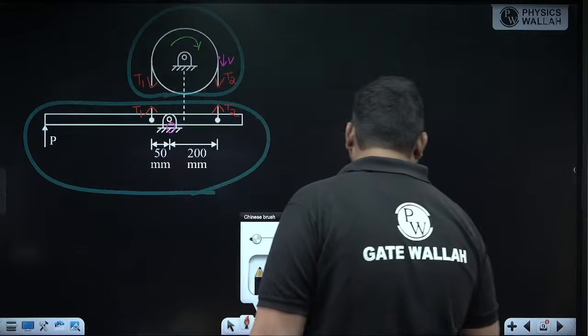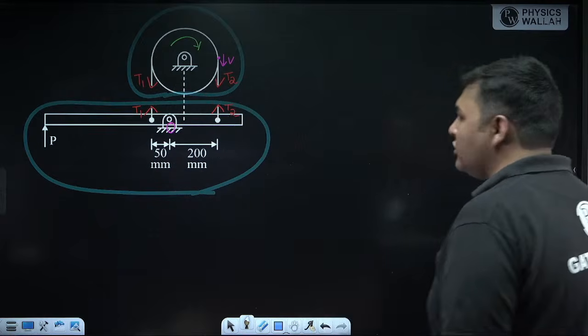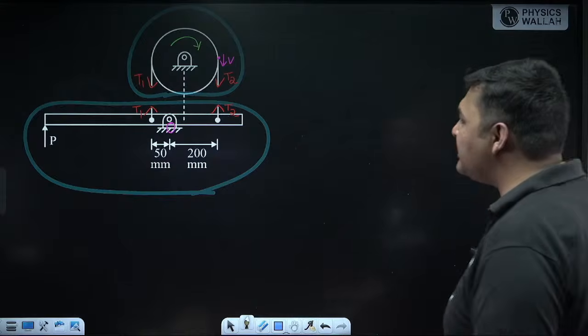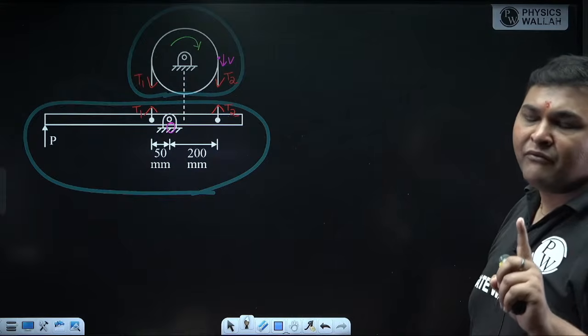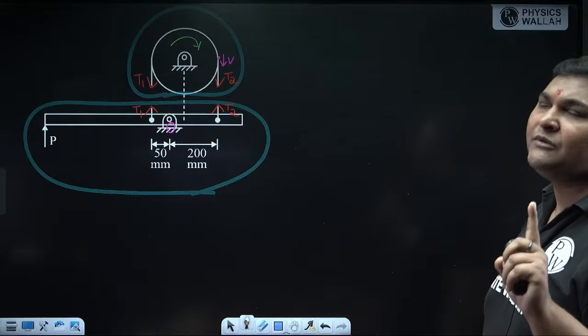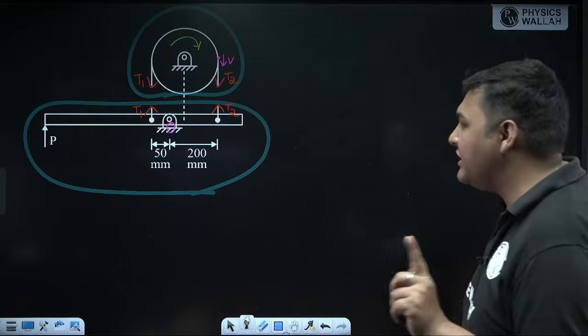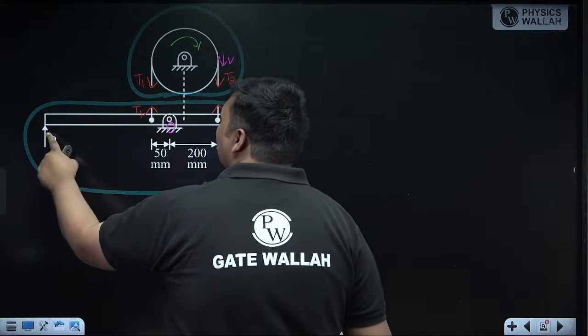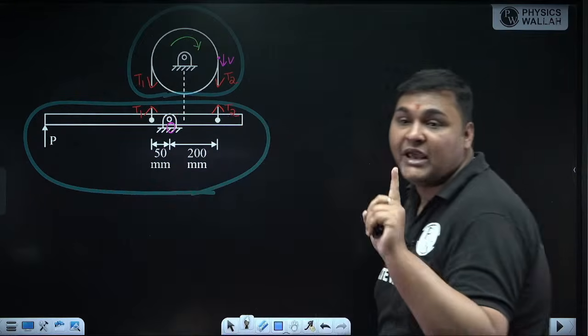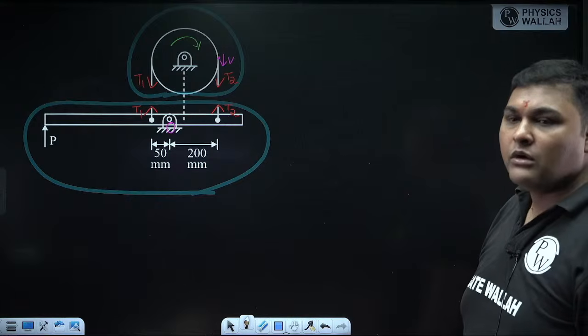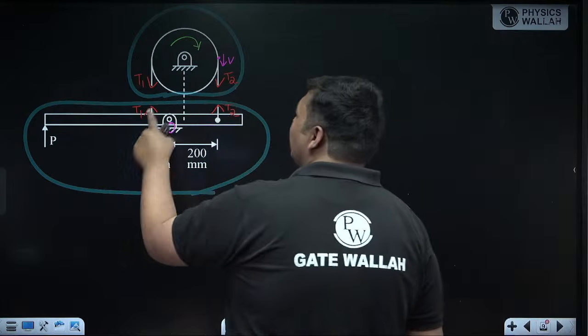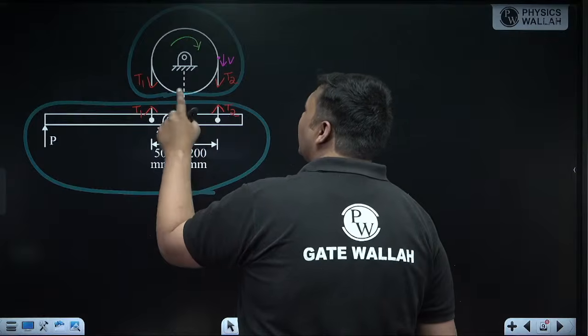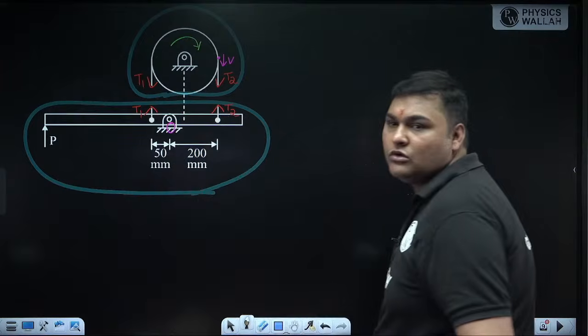Now, to identify whether it is self-energizing or not, you have two approaches. Either you can analyze whether it is self-energizing or not by a trick also. What is the trick now? See, in the FBD of the lever, see what is the direction of the braking effort P about the fulcrum. Always see about the fulcrum. Similarly, see the direction of movement of T1 and T2 about the fulcrum also.